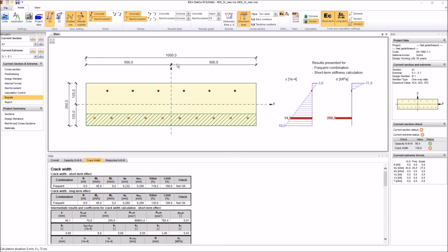If there is another combination in which we get cracks, then based on the settings which I showed, we calculate the cracks. So that's it. If there is no crack from any of the combinations in the project, then we do not check the crack width, unless it is OVS, and then we have to check this stress limitation, the compression reserves, and all these things.